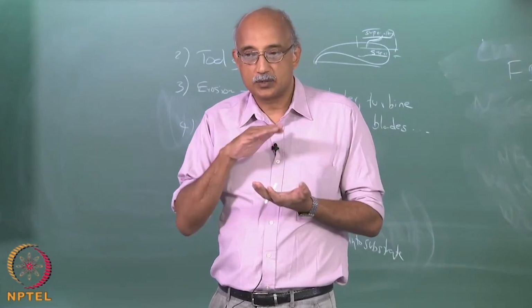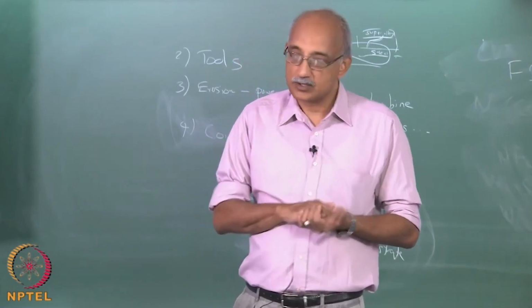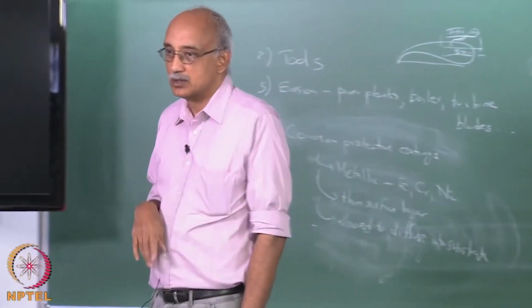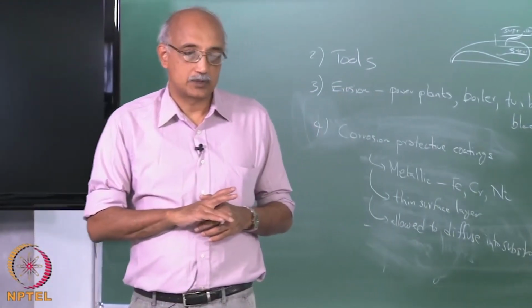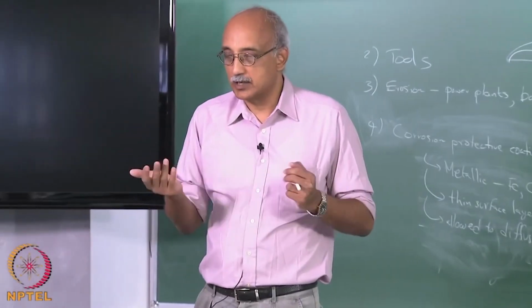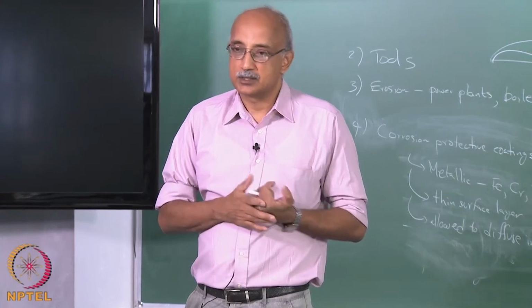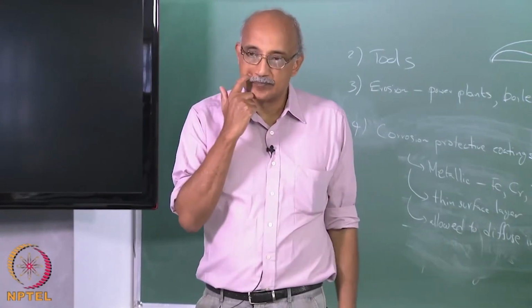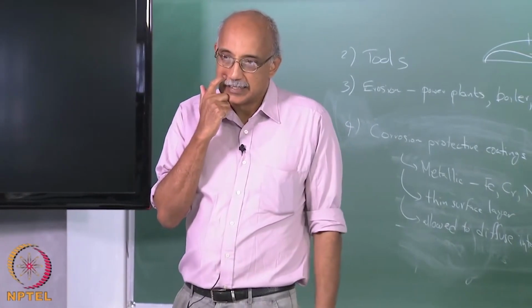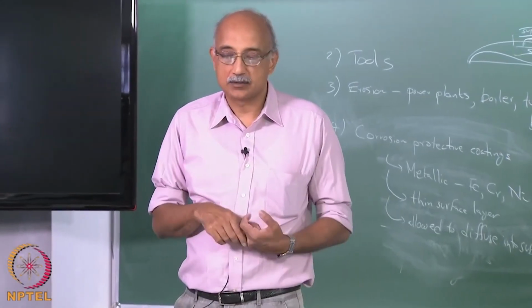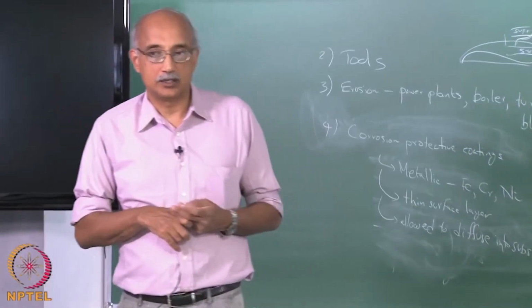But when you are trying to coat a polymer with a metal, that's actually a lot more difficult, because you have to do it without damaging the polymer. And sometimes you have to do that as well, because there are many Teflon devices, particularly again in biomedical applications, that require a metal coating. That is where CVD is helpful. Coating of metals with plastics is not that difficult to do. I mean, there are many different processes that can do it with less complexity than a CVD process.